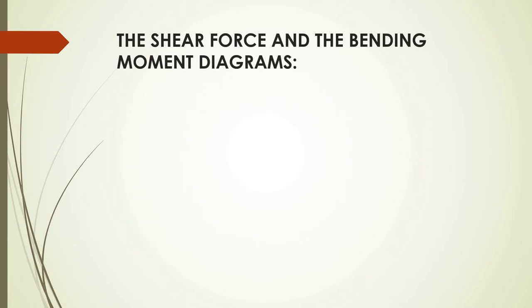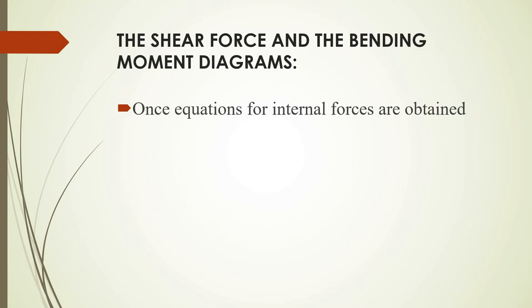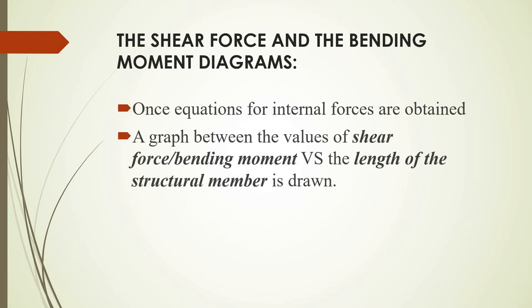Once you're done with all of the sections, with the three equations for each section, you will draw the shear force and bending moment diagrams. These diagrams are a representation of the shear force or the bending moment, depending on the diagram you're talking about, over the entire length of the beam. So they're a good representation of what's happening inside the beam.